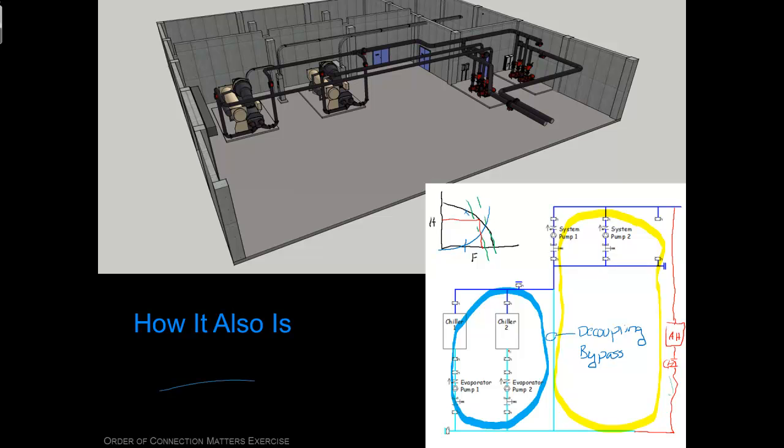In newer plants, you can actually vary the flow through chillers. Current technology chillers with PID controllers, versus proportional controllers, which is what the older chillers had, can tolerate more flow variation. And the risk when you vary the flow is, if you're making really cold chilled water, the refrigerant of course has to be colder than that. So say you're making 38-degree chilled water, the refrigerant temperature is going to be approaching 32. And if it's 32, that's freezing.